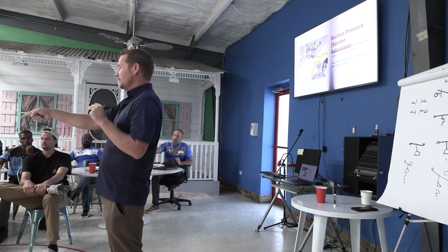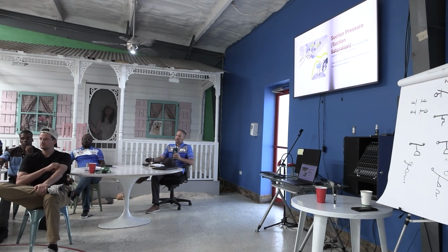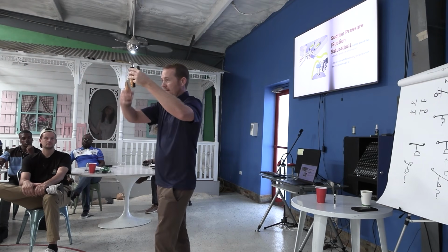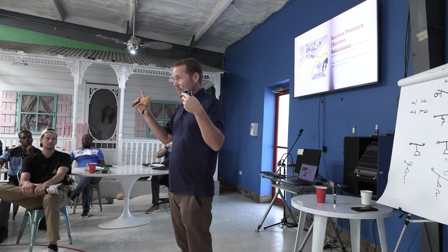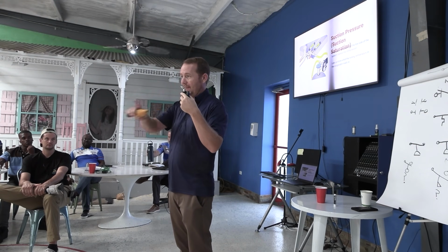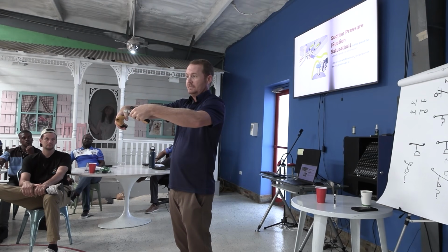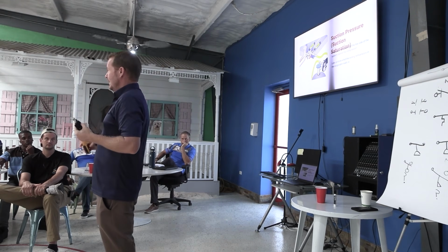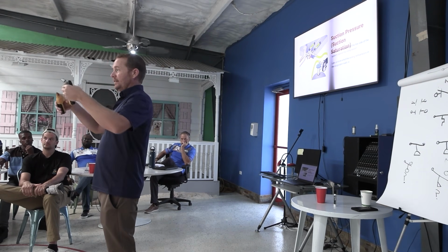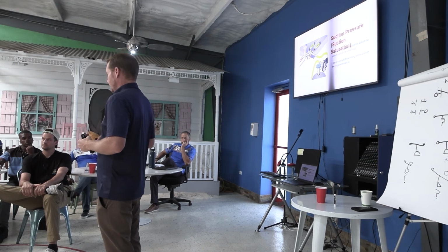Let me grab one of your probes here real quick, just so we can make sure that we're holding that up. All right, so if what I'm measuring in pressure, and that correlates to a temperature, matches what this clamp reads on the suction line, that's telling me that we have liquid and vapor present at that point, if I'm measuring the pressure and the temperature at generally the same place. Does that make sense? So in your suction line, for example, coming back to your compressor, if I'm reading saturation, I'm reading that I have liquid and vapor present at that place at the same time. Is that a good thing in an air conditioner?